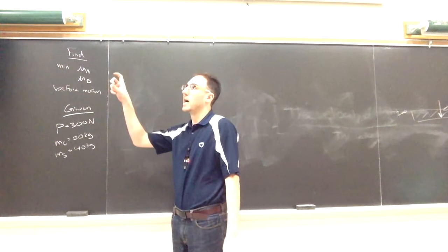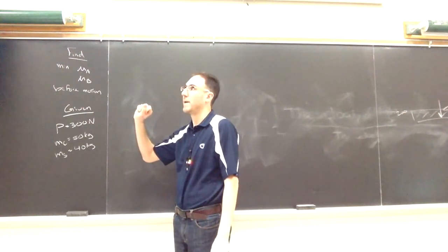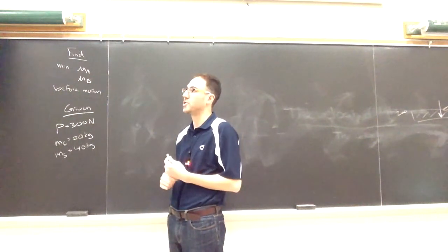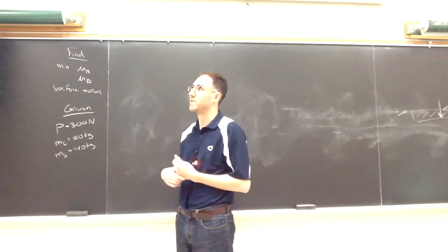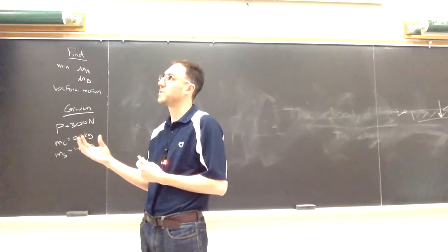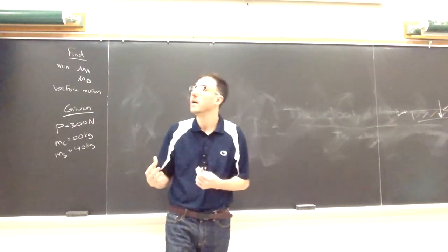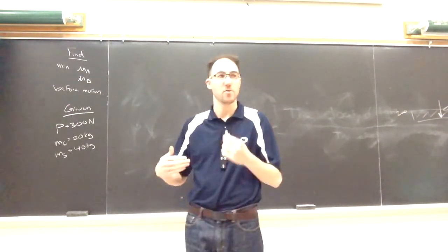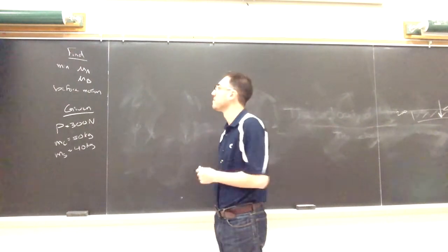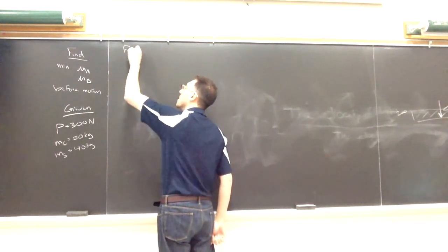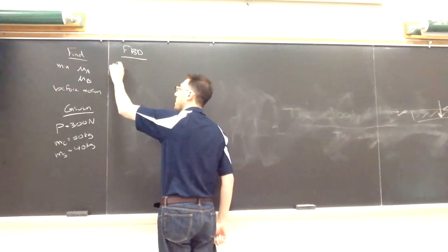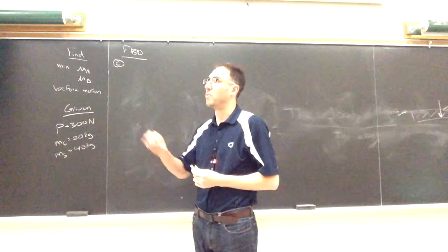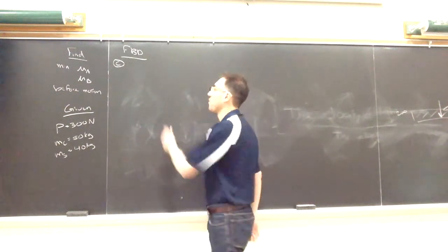The height and the length of the block we don't have information about, so we can't say anything about tipping or whether it's going to try to rotate in that constraint. But we do have some of the information about the spool that we will use. The spool we can treat like a rigid body, but the block we'll just treat like a particle. We don't know where lengths or normal forces are going to be located on it. In our free body diagram step, we'll have block C and the spool, so I'll draw a free body diagram for each of them.